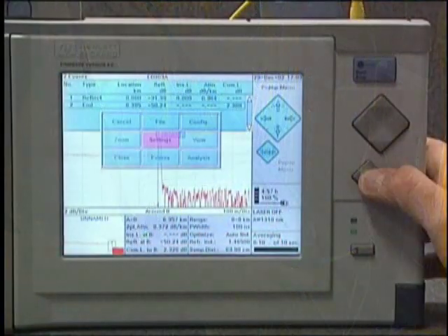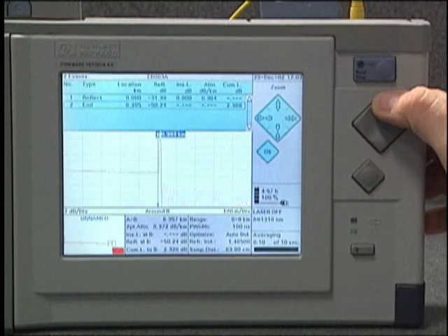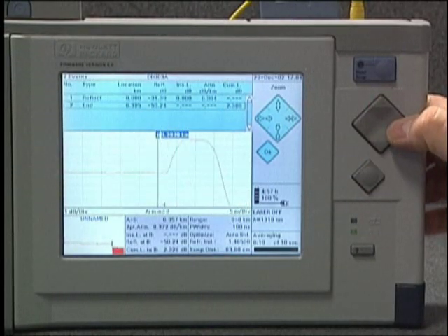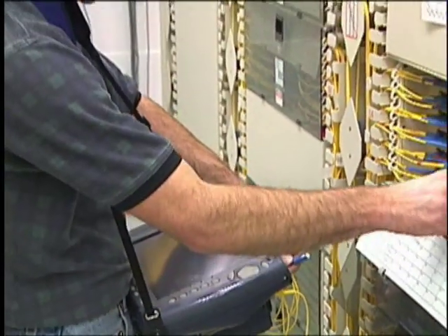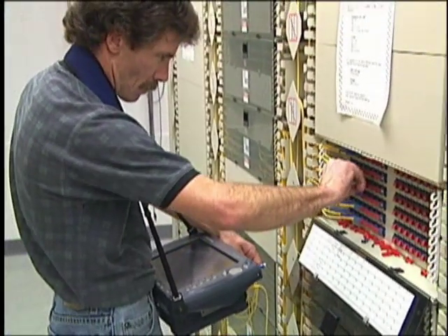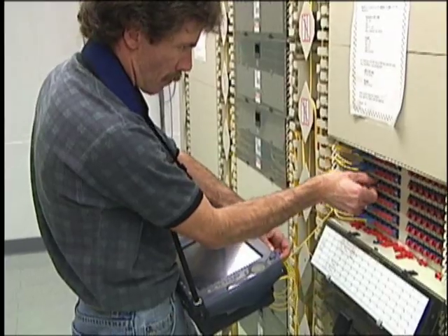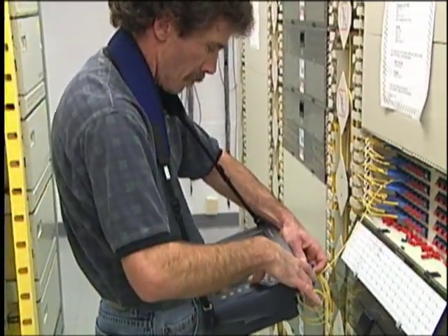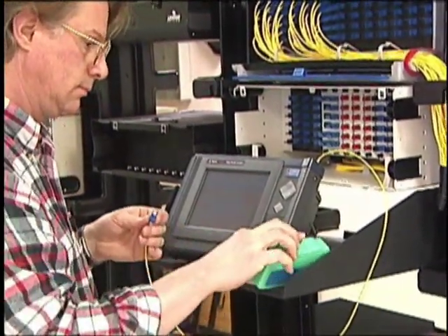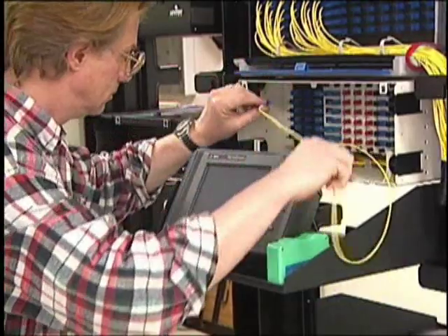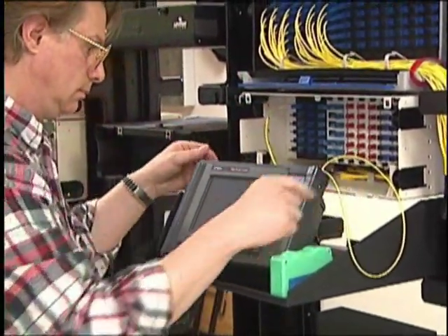Among all electronic test instruments, the OTDR is truly unique in its combination of extremely high dynamic range, rapid acquisition capabilities, and high resolution. Few other instruments used for any test application can boast over 100 dB of electrical dynamic range, together with nearly 1 GHz of bandwidth and a 10 MHz sampling rate, all in the same package. In the following sections of this DVD, we explore some of the performance attributes, applications, measurement techniques, and evaluation criteria of modern OTDRs.